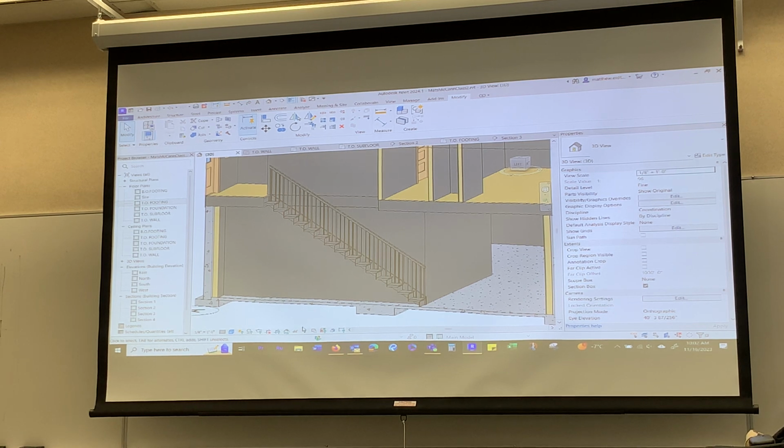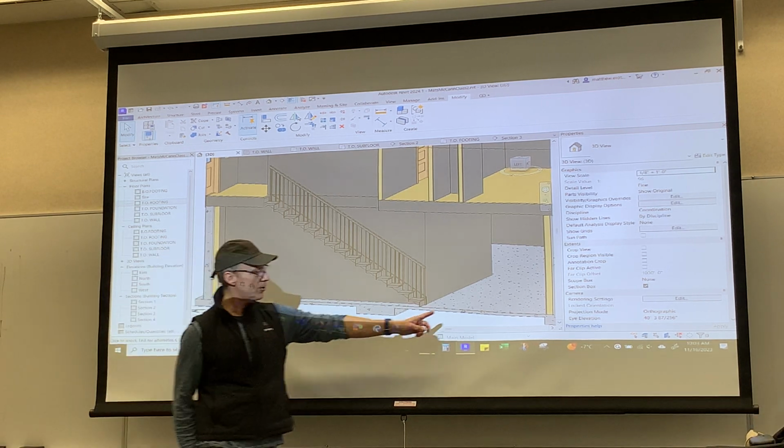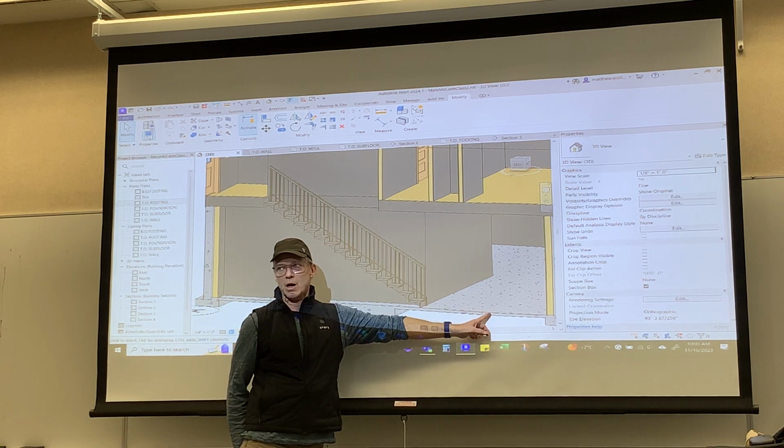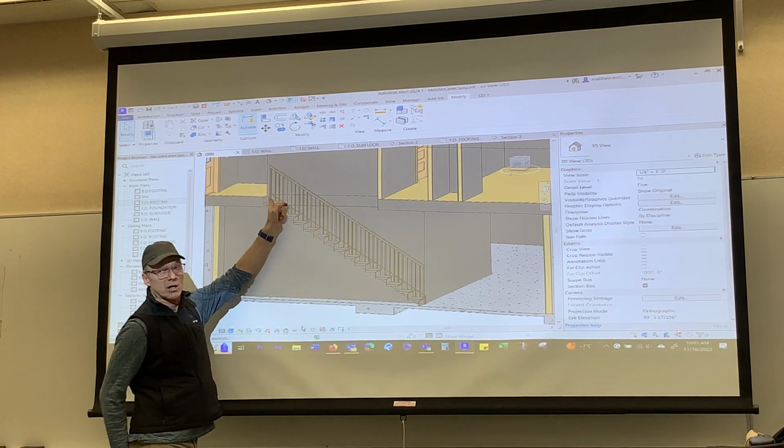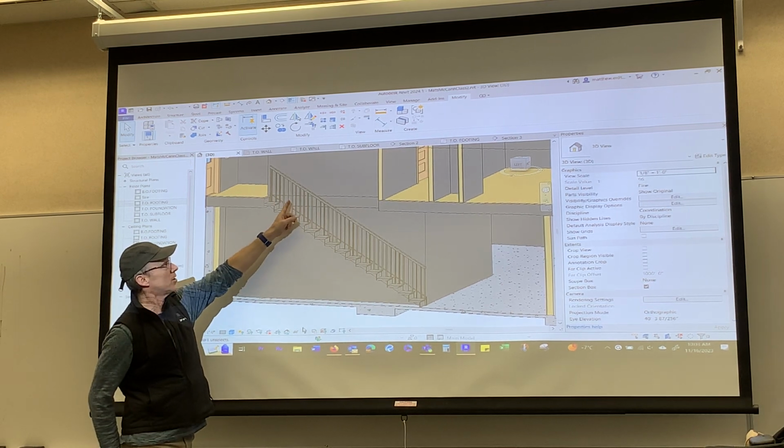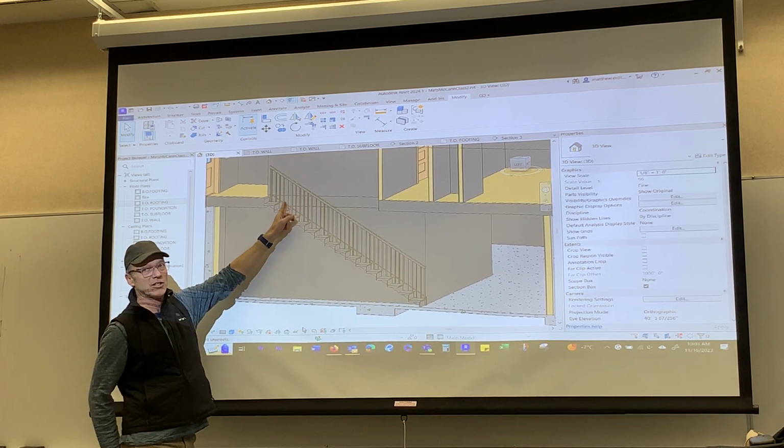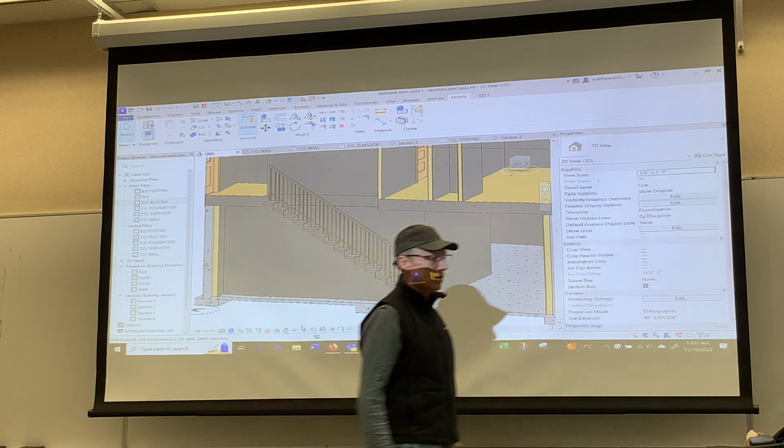Oops, constraints were wrong. Yeah, it's frustrating, but that's probably all it is where you started. Don't try and place them perfectly when you drag them in. You've got to leave some slop. So when you're on top of footing view, when you're first starting, you want to start out here somewhere. And don't be a hero and try and hook it on, because it's not going to work. Leave them back. Not in this view, but in top of footing view.